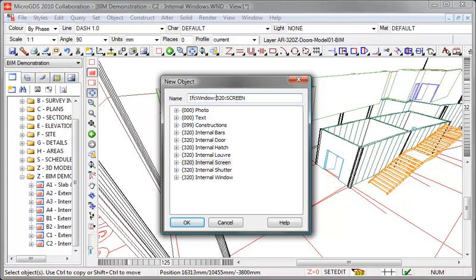Now this can get annoying eventually, that you're having to type this in by hand over and over again. You can in fact modify your naming assistants to include these names, and you can also modify the naming assistant to include the object style that's appropriate for the object that you're creating. So you could have multiple entries in your naming assistant for each different style of object that is available. But for the moment we have to do this manually, so click on OK.